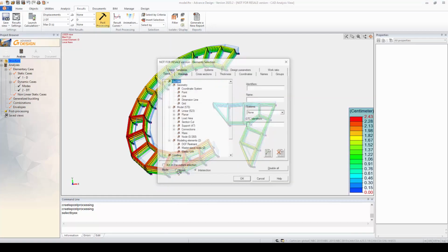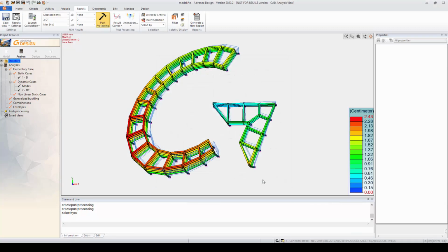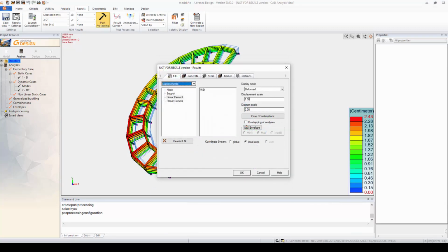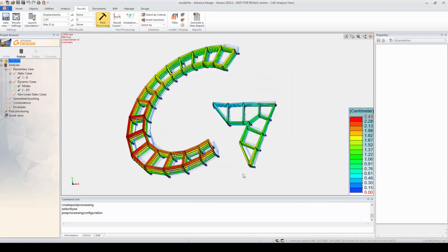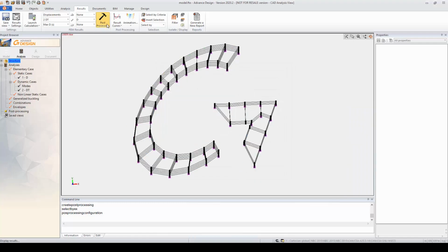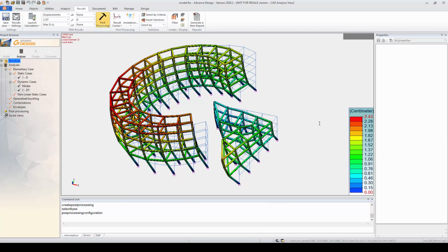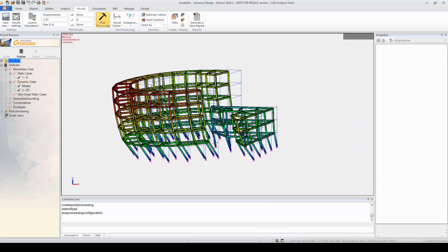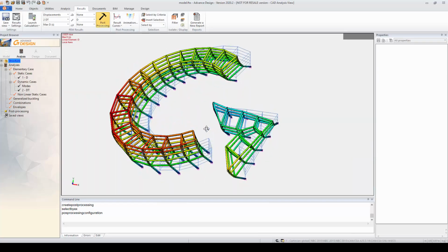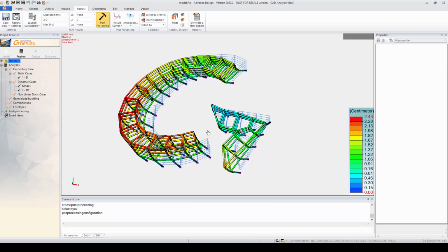You can always change the scale here using the Alt Z and displacement scale. So let's put it as, for example, 3 times. There you go. So I have around 2.4 centimeters of displacement right now, maximum.